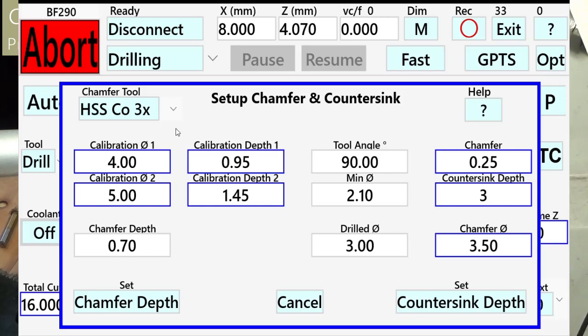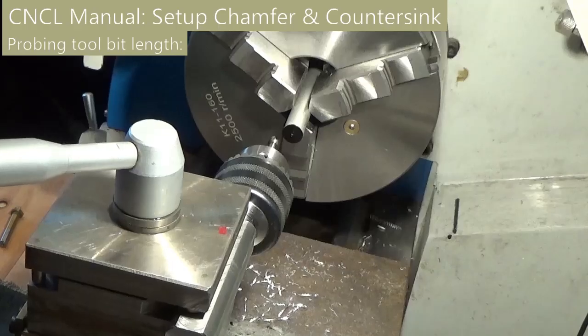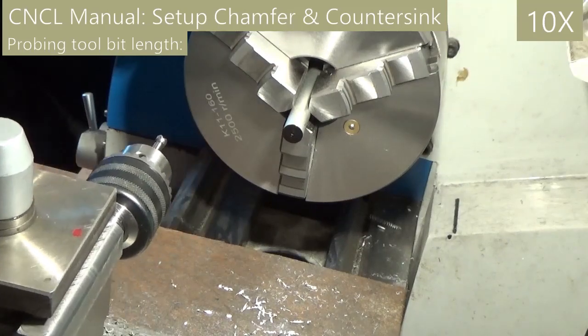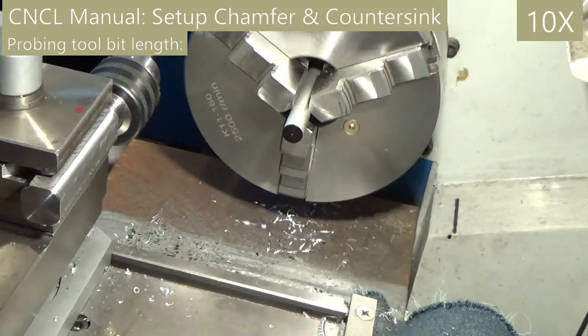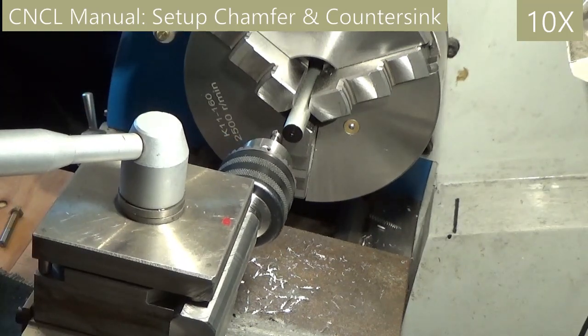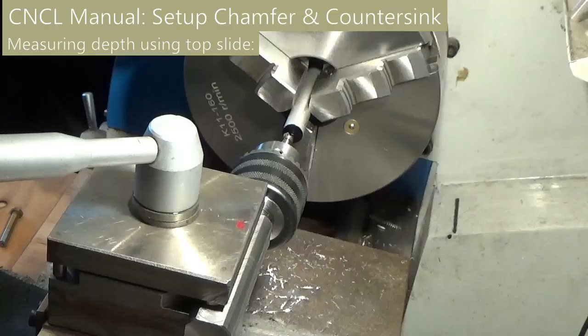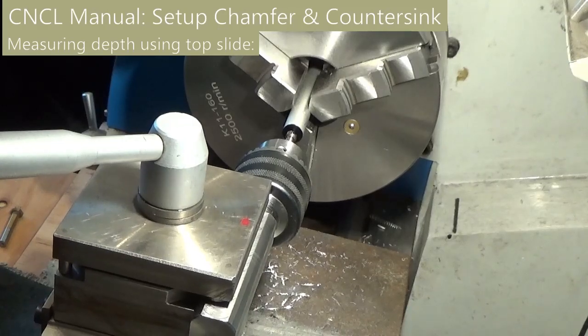So we leave this screen and probe this tool. Now the tool length is set. I can press the go to start position button. This moves the tool to the 0 position.